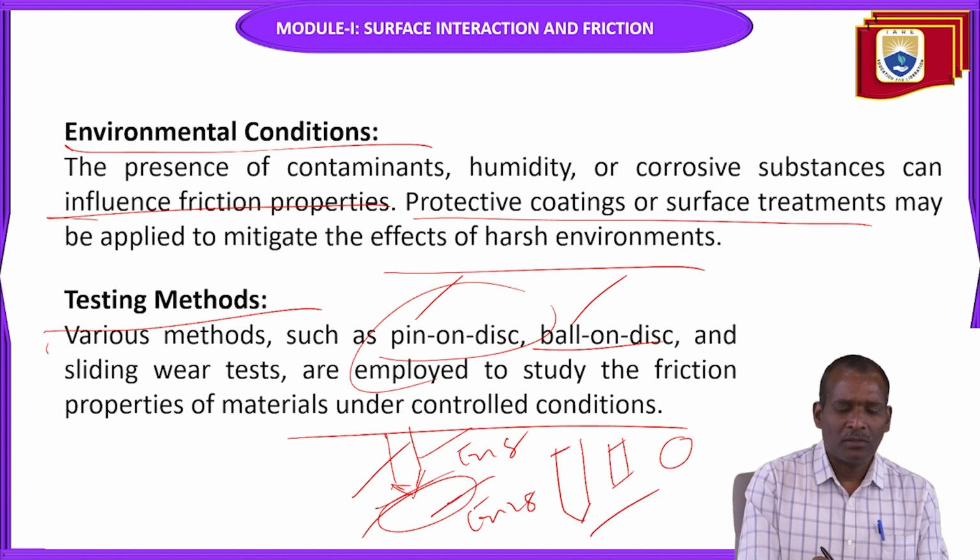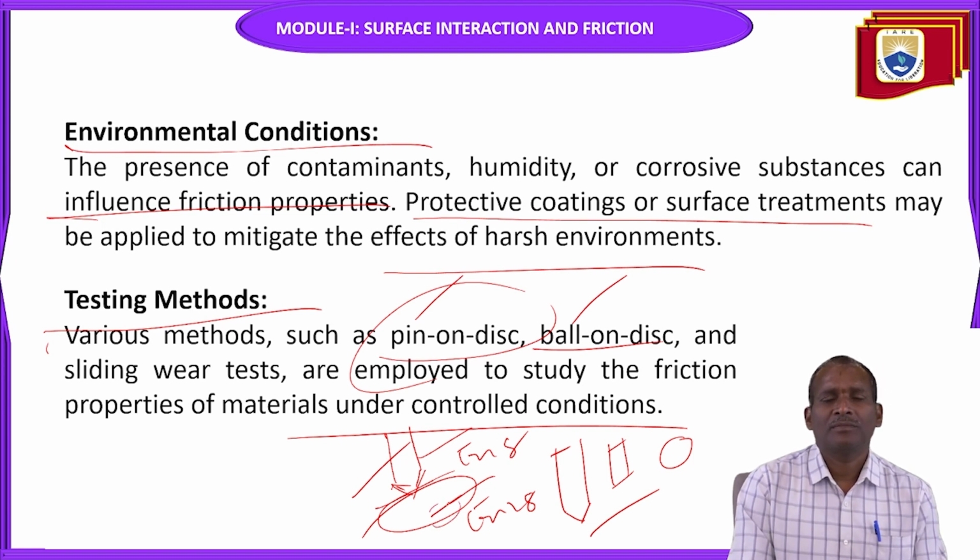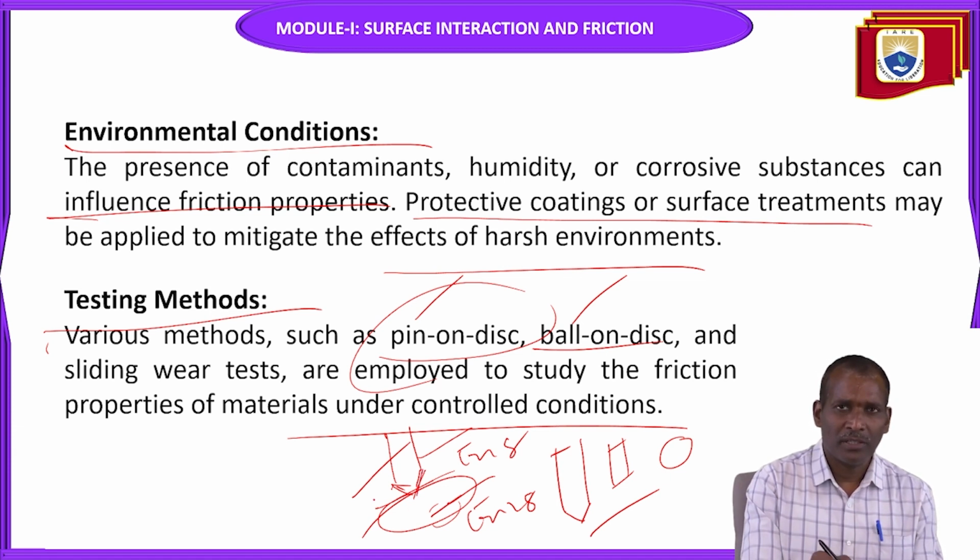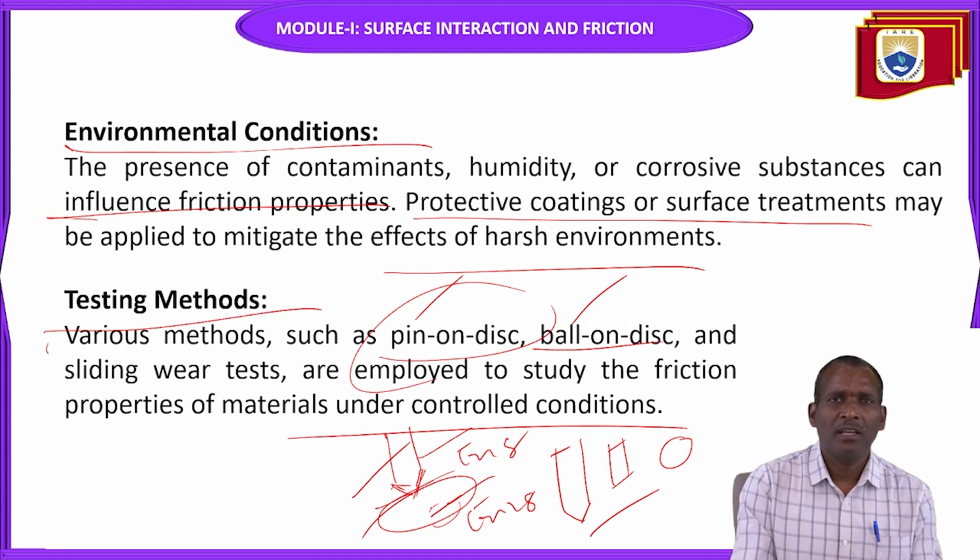The disc always rotates, and the pin moves on the rotating disc. Whenever the disc starts to rotate, the pin touches the disc surface, and after some time, say 10 minutes or 25 minutes, you can calculate the wear of this specimen, how much material is removed.